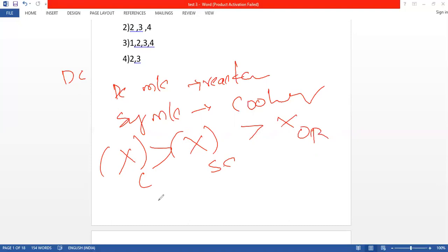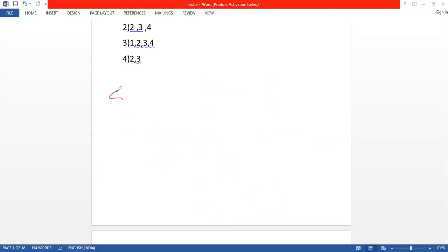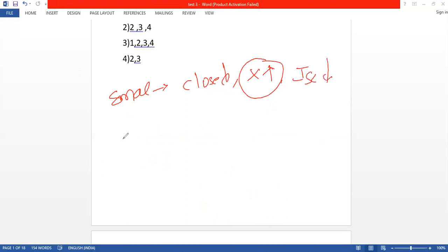So when X is more in closed type, I starting automatically decreases, and inertia of the rotor is less, diameter is less. So speed will increase fast, I starting will decrease very fast. So in small rated machines, closed type of slot is used. Again, in small rated machines, closed type of slot, so X is more, I short circuit current is less. So again your leakage depends upon type of slot also.